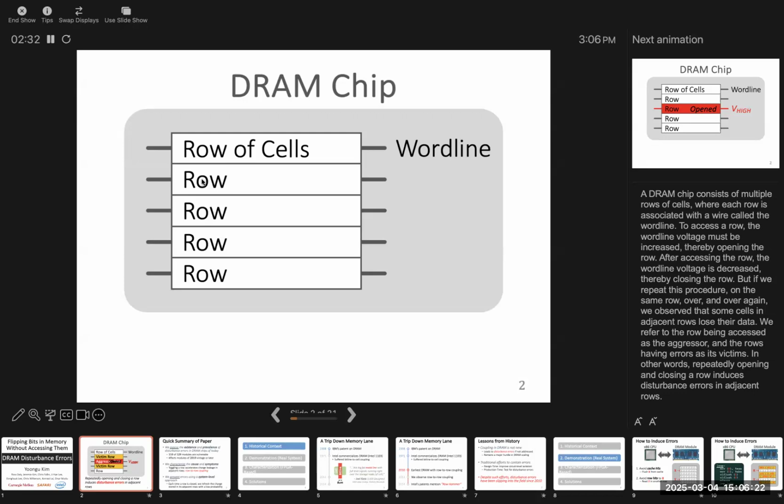So here they are using some terminologies. As I said, I will use the background slides later, so it will become clear to you what a word line is. But a word line is actually a signal which you need to activate to enable reading or writing from one complete row of the memory array. So if you enable the word line, only then can you either read the data out of the whole row, or write the data to the whole row.